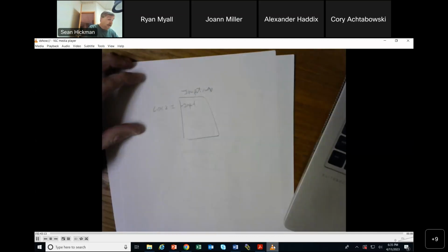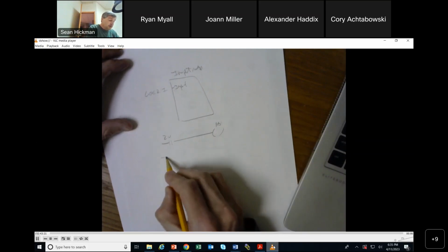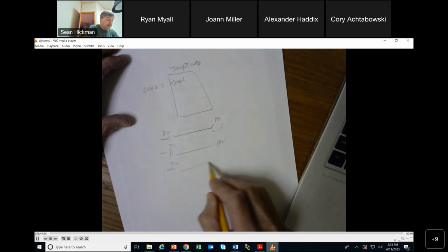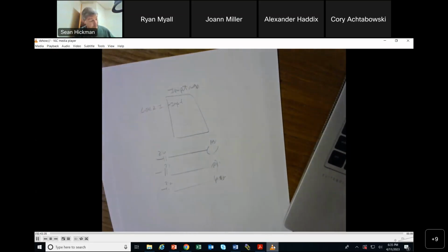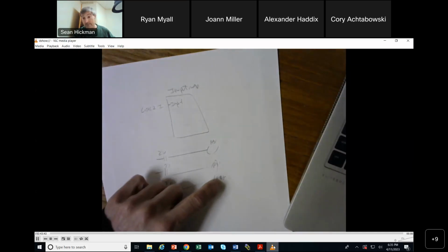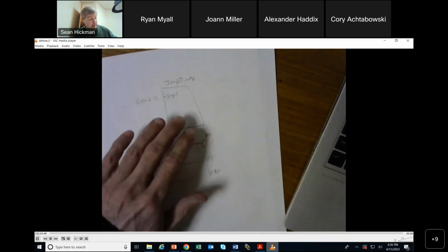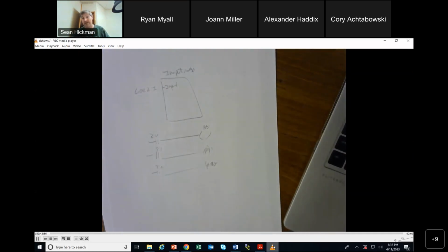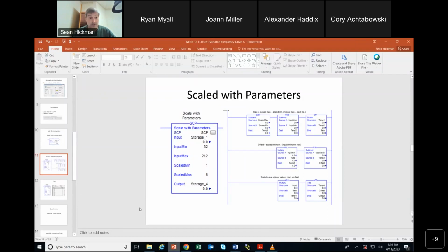What would the logic inside of here look like? It would be 2.0 is PB1, 2.1 is PB2, 2.2 is PB3, or whatever you want to call these. So you just drag this in, put whatever module you've got there, and bang, it's all mapped. PB1, 2, and 3 might not be the best way to do it, but if you have another set of inputs, just drag that input map AOI in, and you don't have to program it because it's kind of redundant. So that's one way that people might do input mapping, with an add-on instruction.